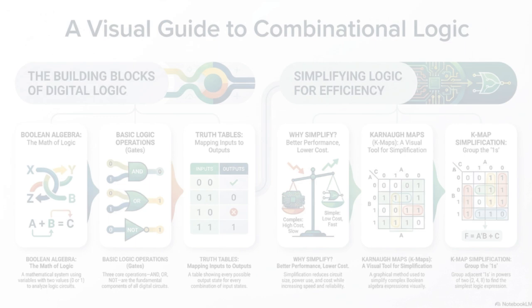You mentioned the math for the XOR gate. It's written as Y equals A times the complement of B, plus the complement of A times B. That looks complicated on paper. It does, but let's just translate that into plain English. That equation is just saying the output is 1 if A is true and B is false, or if A is false and B is true. So, one or the other, but not both. Exactly. It's the condition of exclusion.